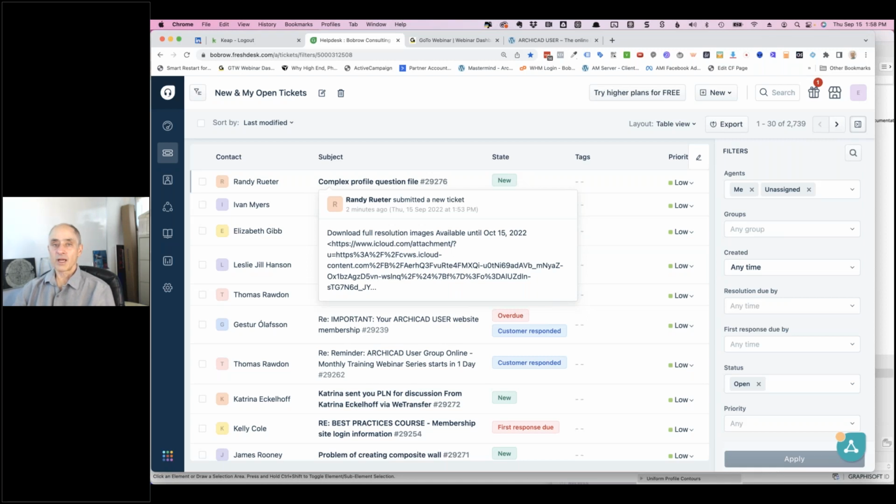Putting it on a negative story is fine. I like putting it on a layer that's hidden, so that way it can literally be in a convenient location, but not seen unless you want to see it. In Master Template, I have a layer specifically for object creation. While you might have things initially on other layers, my suggestion would be to select all the elements that are part of that object, put them on this special layer, and then hide that layer until you need it. You might also group those elements so that it's easy to select them and move them around.